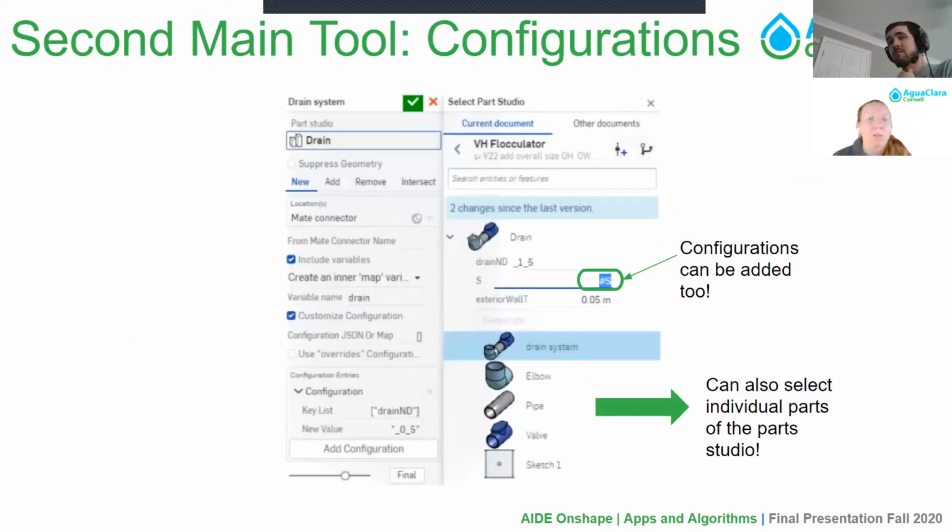One of the benefits of Derive is that it can cut down on the number of configurations used. In the assemblies, we had transferred over basically every single configuration that each part studio used into the assemblies configuration. This resulted in assemblies with hundreds of configurations, leaving an unorganized mess of configurations. With Derive, configurations of the derived part studio can still be altered based on other configurations as seen in the figure on the left.